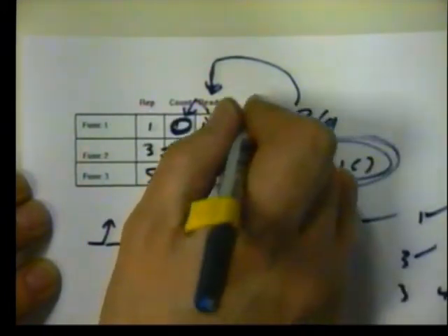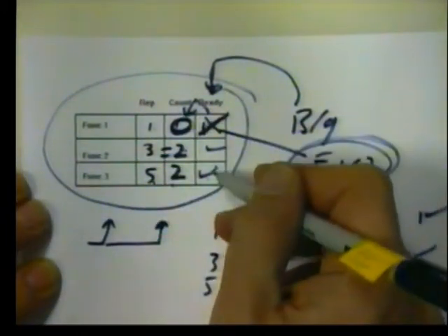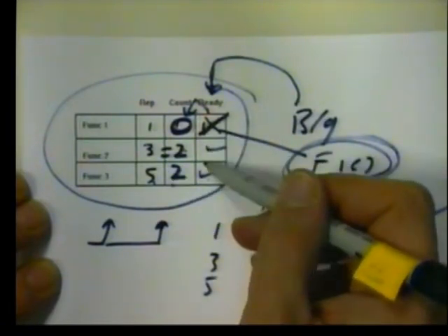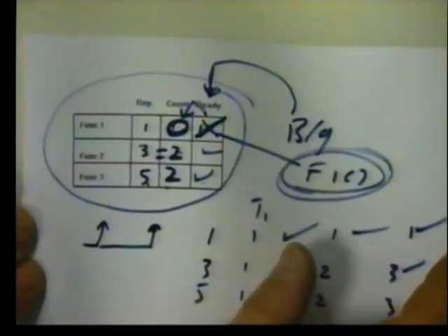And so by a simple mechanism such as this, we're able to schedule 3 different functions to run at 3 different time intervals. And all these time intervals are units of 100 milliseconds. Then we took the thing further. So we now have our mechanism. We have a real-time interrupt executing every 100 milliseconds. It's checking the repetition rates, it's incrementing the counters. If there's an equality, it's setting a signal that a function is now ready to be scheduled to run. The background routine has to scan that all the time and execute it.